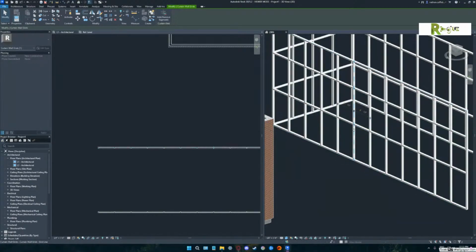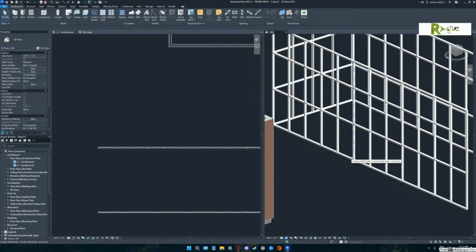Pick it. When we pick a grid line, one of the things that we can do is add or remove segments. Do you see where that's at on our contextual menu? Right there. That's it. Hit that and pick that mullion at the bottom. Go over the curtain grid. Right there. Up a little bit. Just a little bit up. And pick. Try hitting the actual line.